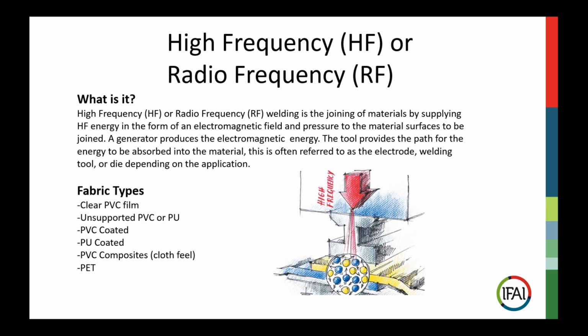The tool on an HF or RF machine is simply providing a path for the energy. And it's not the thing that gets heated up, but it actually may get hot from the heat of the material reaction. So something good to remember, though, about RF tools is that they are very quick and easy to change in and out, and they're relatively inexpensive. So you could be doing a high variety of tasks with the one machine.